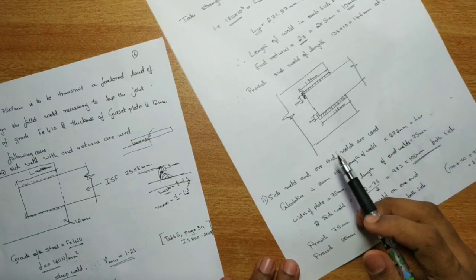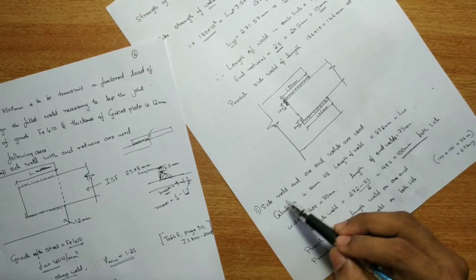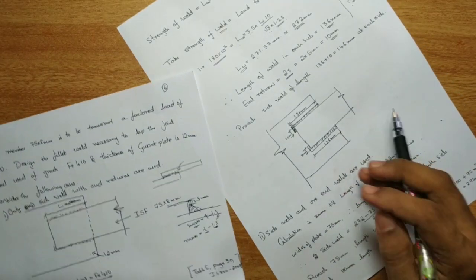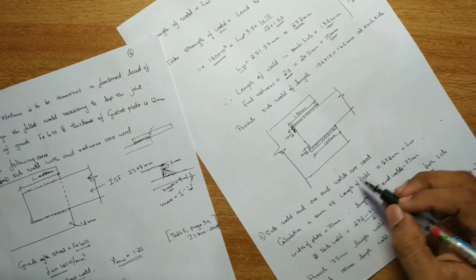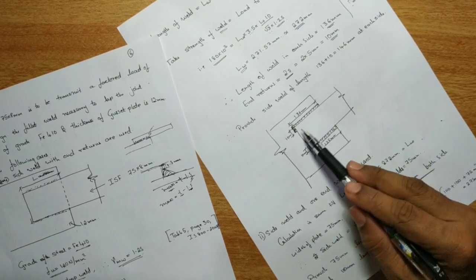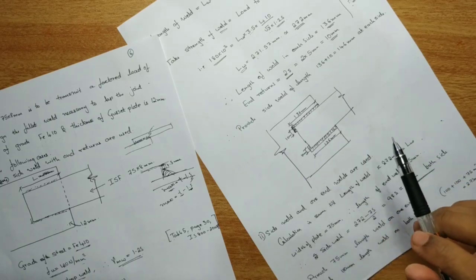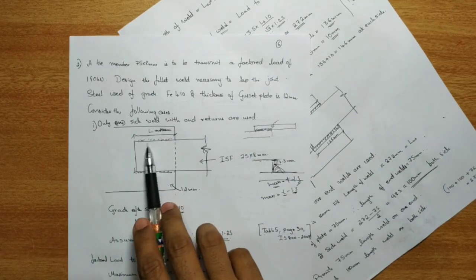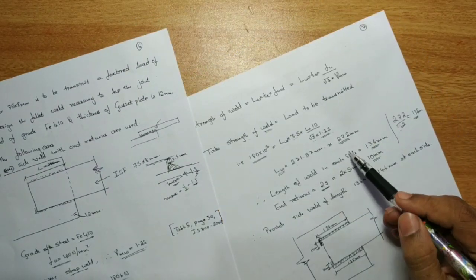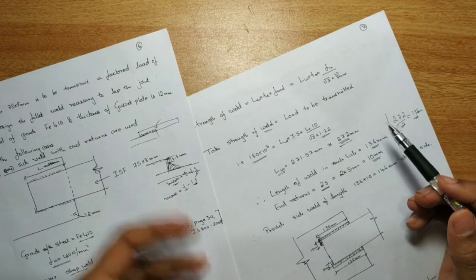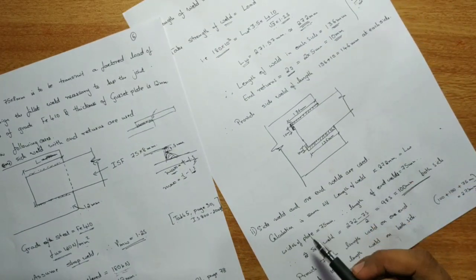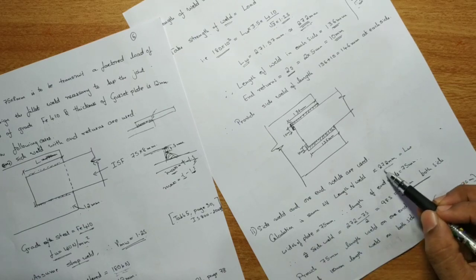Okay, now let us go for the second case here. You need to provide side welds and one end weld here. In the previous case you took only the side weld. Here you need to provide 3 sides, 2 side welds and 1 end weld. Fine. Up to this 272 calculation, it is the same. Now just the distribution you need to change here. For the distribution, the total calculated LW is 272.